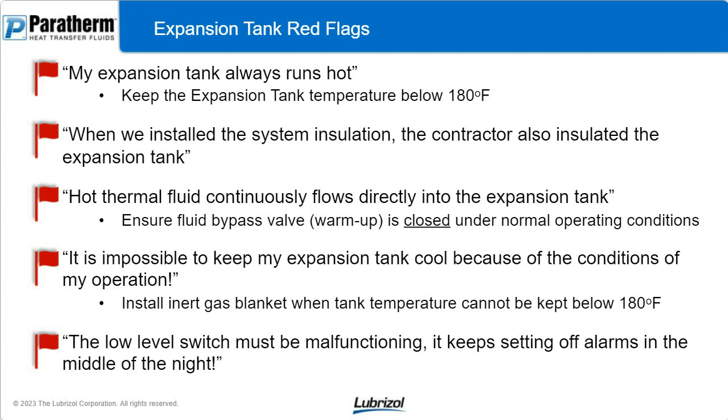Sometimes there's buildup of solids in that tank, and you want to make sure that float switch can actually move up and down. So just go up there when you're checking the temperature of that tank on a regular basis. Just try to manually move that float switch and make sure that it's actually functioning properly.